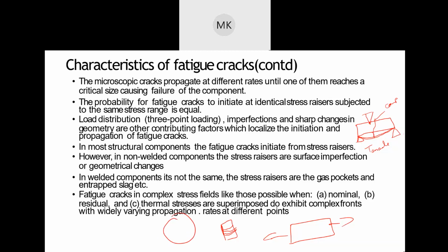The way 3D printed metals work is basically you have a powder bed, a bed of metal powder, and I'm applying a laser or any other heat source to fuse them together for a small layer, and then I'm going to build another layer on top, build another layer on top, and keep going like this. The advantage of this process is, if I have the money, I can control the rate at which I'm building the material and also make sure that the fusion is pretty good.